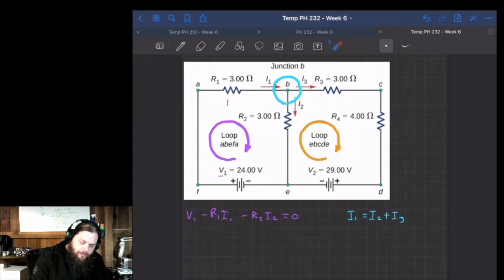And this time our current in this middle one is going downwards, the same direction as our loop. Because they're in the same direction, we have a voltage drop across this resistor. Last time our current was going up instead of down, so it was going the opposite direction of our loop. That's why we added the voltage of that resistor. Here we're dropping that voltage down.